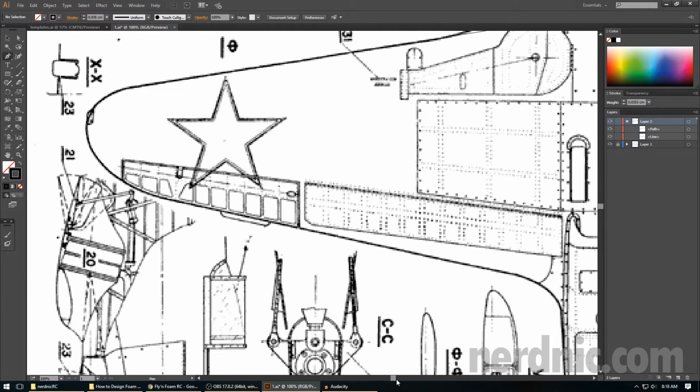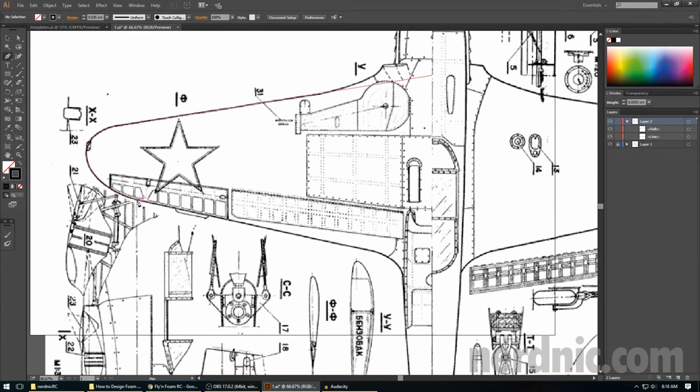Alright, so we've got that part. I'm going to zoom out a little bit, and now we're going to go ahead and finish this straight line, because it's almost always a straight trailing edge. And so I'm going to find my anchor point. I'm going to click and hold, and I'm going to draw to the point where, if you notice, there's a purple line that just appeared. What that purple line is telling me is I am at the same axis now as that top line up here. I'm at the same depth. And so if I let go, then these will be perfectly in line, right? One on top of the other, which I want. I don't want the bottom to extend out or be too short.